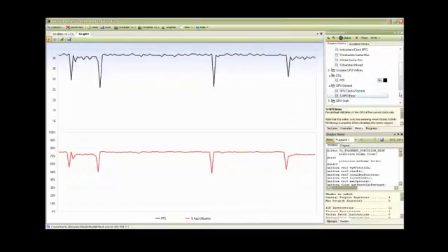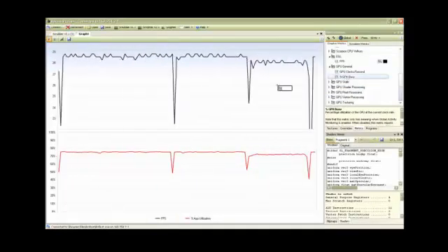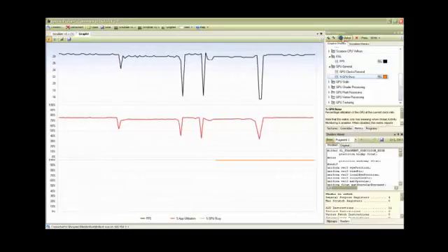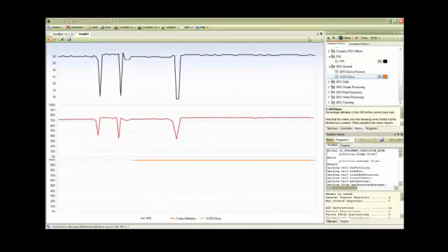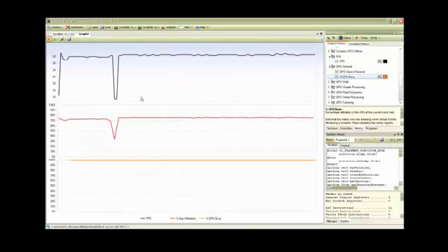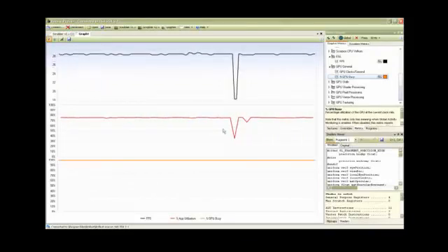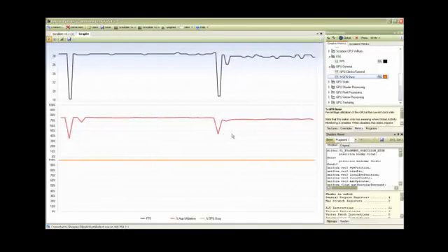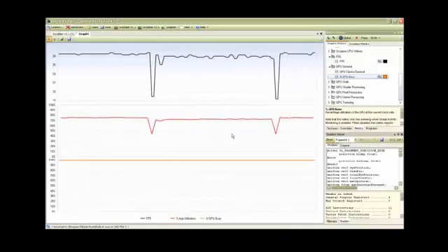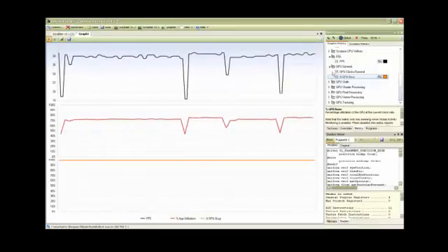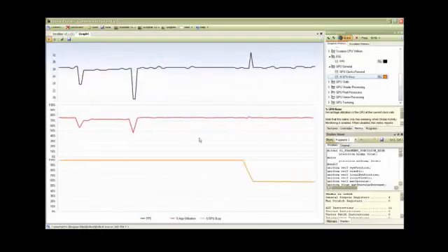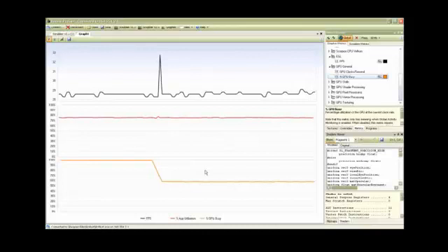So we'll grab GPU busy percentage. One thing you'll notice here is there's this global button. So what this means is that normally when you're profiling an application, it's looking at metrics related to a specific OpenGLES context. Normally that's what you want, but there are times when you might want to view the entire system. And when that's the case, you can just click on this global tab, and now it'll show the usage of the GPU of your application relative to the entire system.